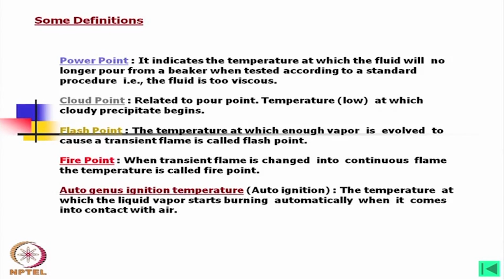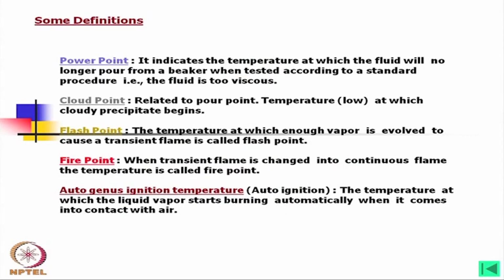Now, this may happen where the temperatures are very high. So, we have to cool the oil we are using, and we have to make sure it does not reach the auto ignition point. Here I would like to mention that usually the mineral based oil temperature may be up to 75 degrees for safe operation. Normally in our country the ambient temperature in summer may be 45 to 50 degrees centigrade inside the factory, a very hot summer. At that point oil temperature may go as high as 75 to 80 degrees centigrade, which is very close to the flash point.